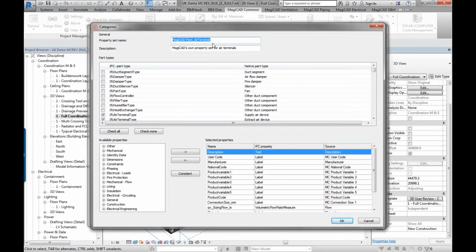So all you're doing is building up on the right hand side any categories of object and then any parameter about that, and then once you choose a target file here, you just export to a spreadsheet. Once you've done that, you manipulate all the data, and then just go spreadsheet import, choose the file, and bring it back in again, and it updates all the values for you. So that's quite a straightforward tool, very, very useful though, of course.